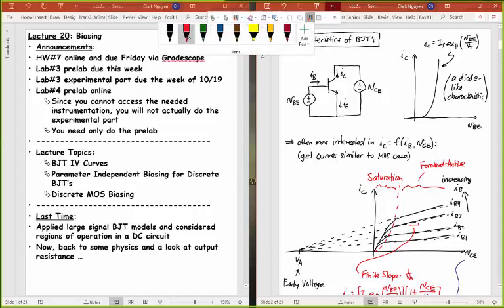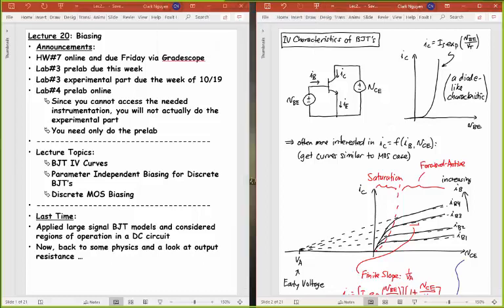So if I took a closer look at this, I would be able to identify that if I look this way and I'm looking at the resistance there, then that resistance I'm often going to call R0, which is going to be a small signal resistance. And that actually is going to be equal to the small signal quotient between VCE and IC.